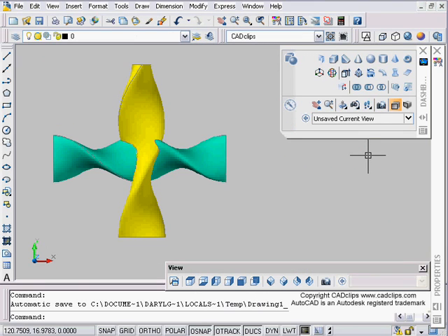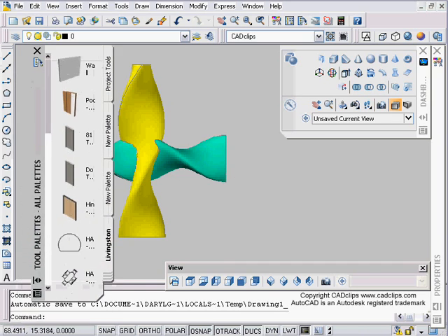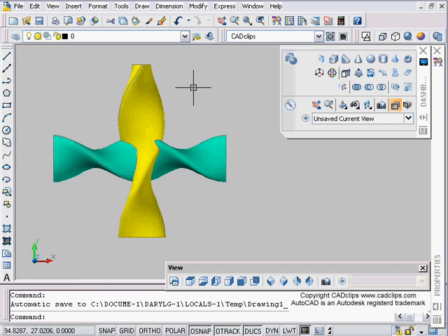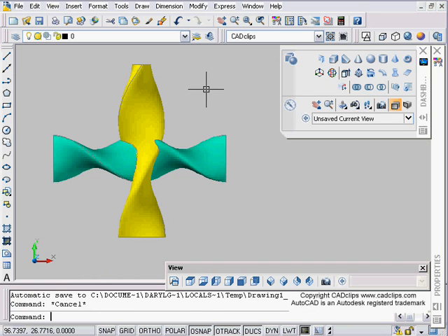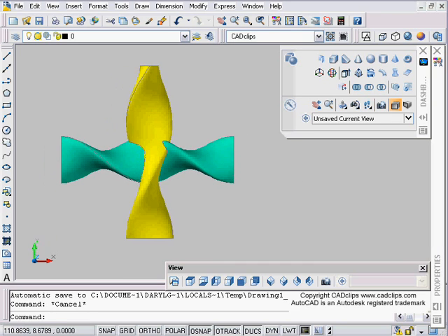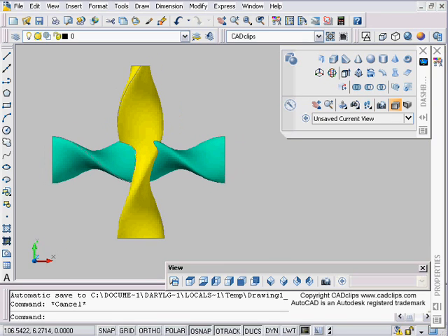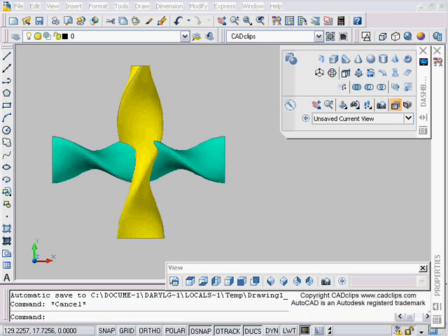Hello and welcome to another CAD clip, AutoCAD 2007 3D. In this lesson, we're going to talk about the new sweep command. The sweep command is nothing new. The difference is that the interface is a little different, and you don't have to align the profile you're sweeping with the path. So that part has improved, which makes things so much easier for us trying to teach 3D, because you're having to use your UCS a lot less now, and it's become a lot easier and more intuitive.